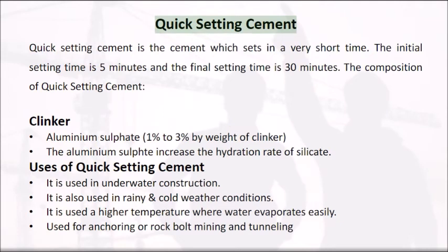Quick setting cement. Quick setting cement is the cement which sets in a very short time. The initial setting time is 5 minutes and the final setting time is 30 minutes.